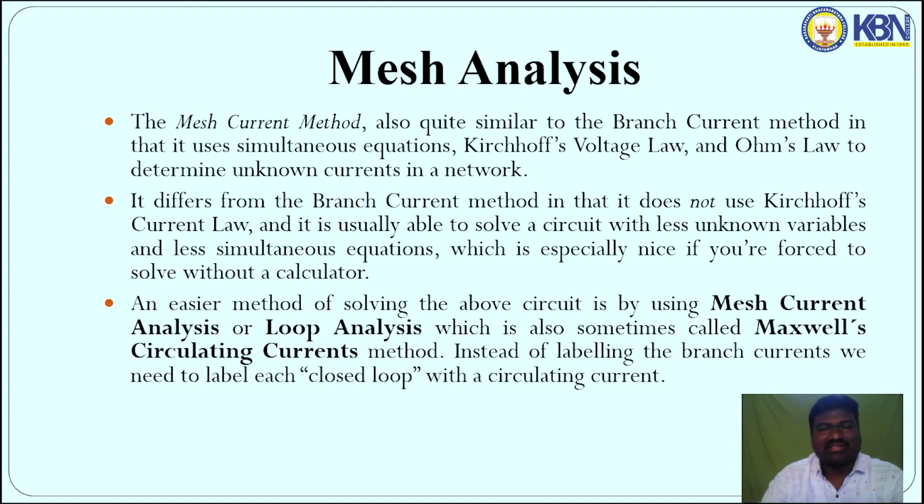Next, these laws are mainly used in mesh analysis, the branch current method and the node analysis method. Firstly, we are discussing mesh analysis. The mesh current method is also quite similar to the branch current method in that it uses simultaneous equations, that means Kirchhoff voltage law and Ohm's law, to determine unknown currents in a network.